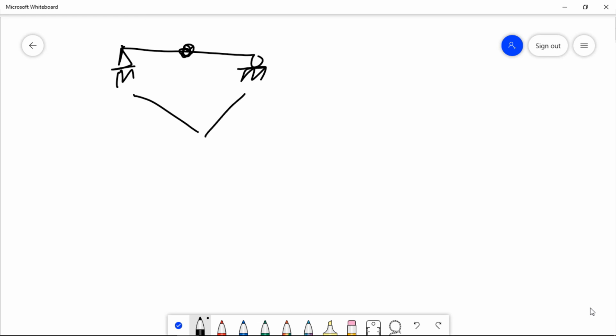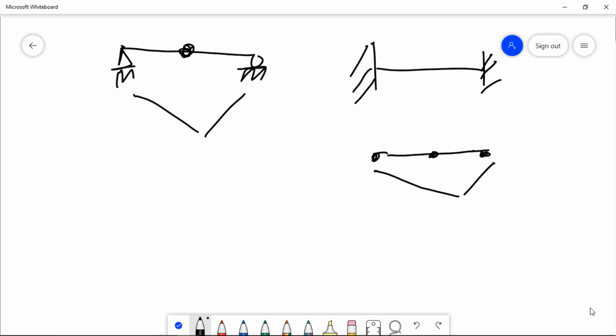Similarly, I have shown in the fixed-ended beam, failure will occur. First the yield points at the supports will form, which will act as hinges, but the beam will still not fail. The beam fails when a hinge forms at the center. Now the whole beam does not have the capacity to resist the moment. Now the beam will fail. There are no stable elements due to the hinge formation at the center, so the beam will collapse.